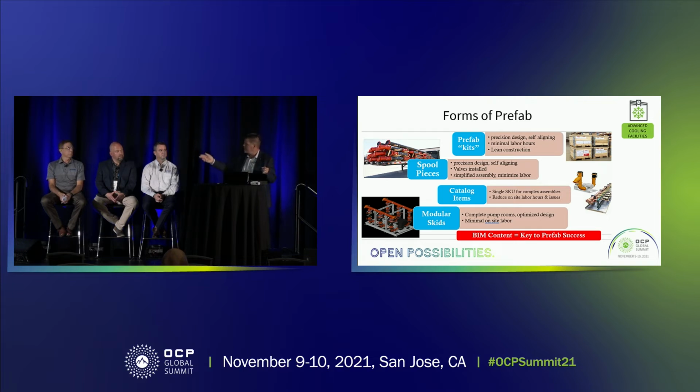You want to unpack that a little bit, John, Mr. Masilli there? What are we looking at there? So you could start with things that are as small as a bread box, literally, right? Just a little VAV that's going to go up in a ceiling somewhere, with its electrical connections on it. And then you could go all the way up to full 600,000 CFM air handlers that would be in a couple of components, but could be bolted together on site and online within 2 or 3 days.